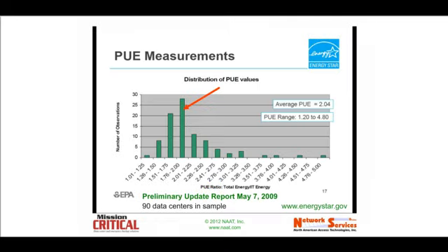So to sum up, the 2009 Energy Star program discovered that the majority of data centers pretty much came up with a PUE of 2, the proverbial number that's quoted by everybody. But with the advent of free cooling, we really can see how we can bring our PUEs down, way down in the 1.2, 1.3 range easily without any extreme methods by using outside free cooling.